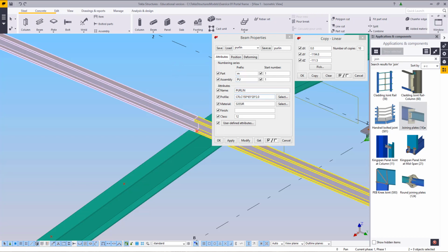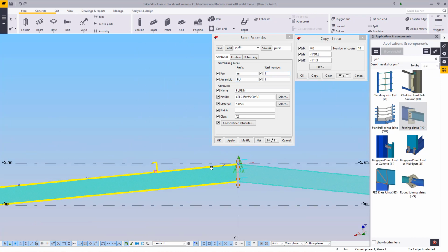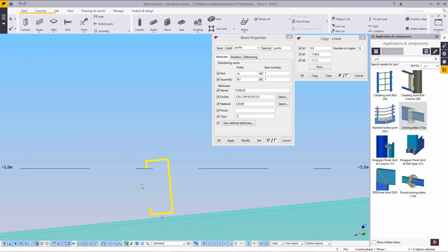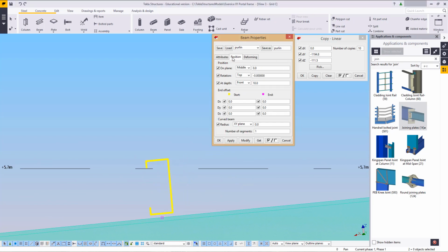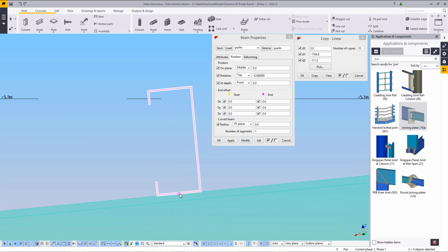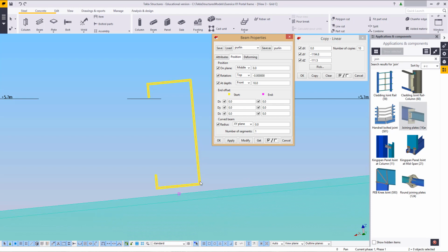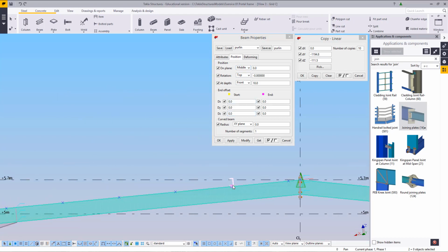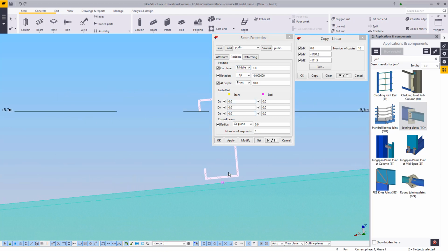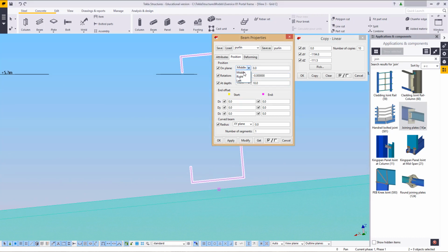Right. From here, I'm going to go back to grid line C, and I'm going to have a look at this. Now, as I said earlier, they've got a 10 here. Basically, front is right at the top, and then 10. This 10 is for the cleat, so that it's got welding on the inside, and I'll show that when we get to it. Next, these marks that I'm using currently are not the center of the purlins, rather they are the back of the purlins.